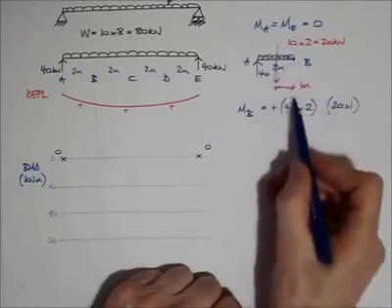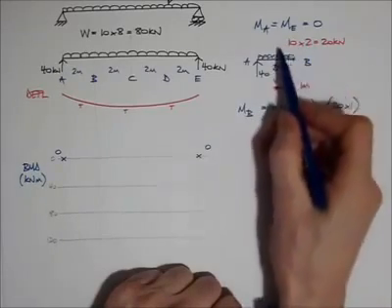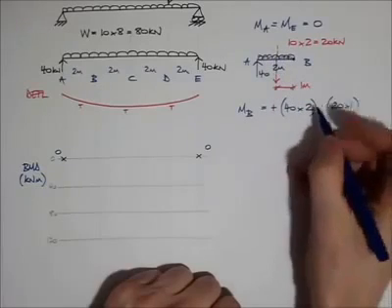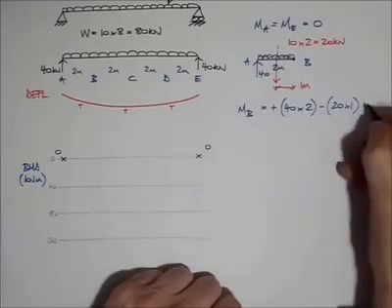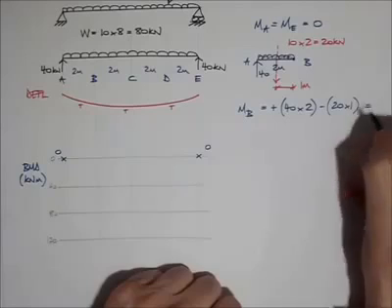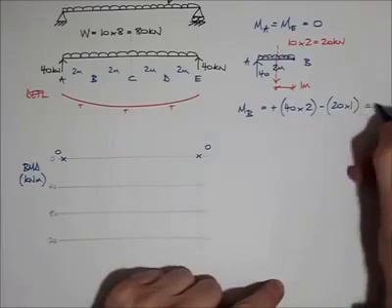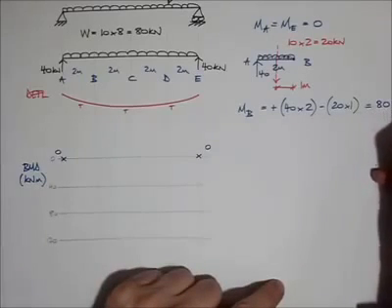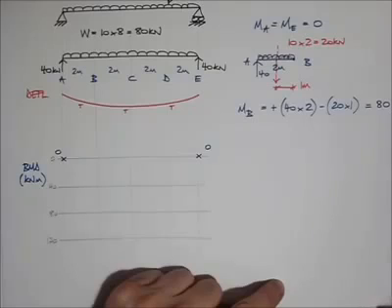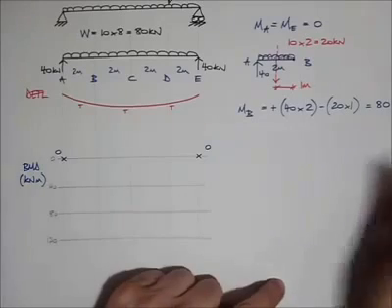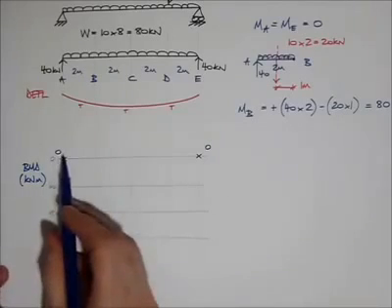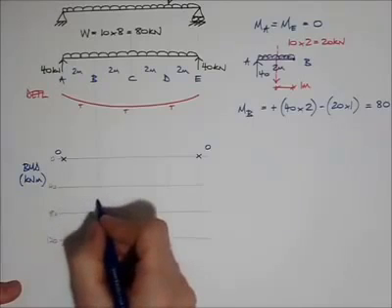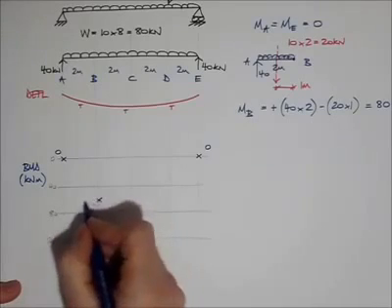So the bending moment is 20 times 1. Now that would be going anti-clockwise around point B, so that's negative. That's all the forces I can see, so I need to calculate that. That's now 80 minus 20 equals 60 kilonewton meters. Great, I can go to my bending moment diagram and just add that on: 60 kilonewton meters.